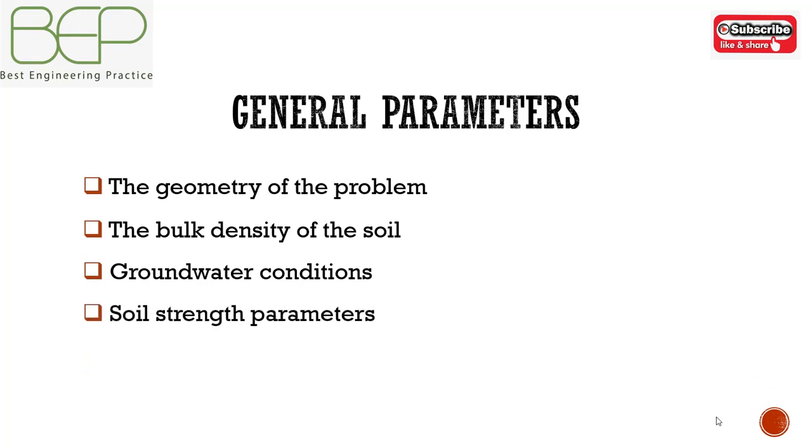Soil strength parameters. This will vary according to the type of problem. In general, the designer will require knowledge of the peak effective strength parameters for the soil that the wall is to support, since active earth pressures are nearly always very much greater in the long term than the short term.